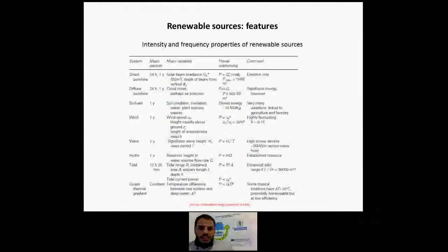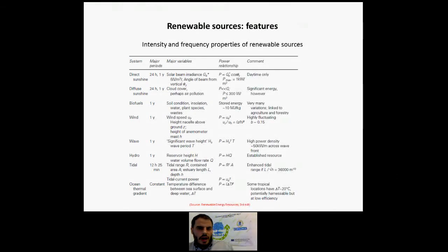With electrical systems, the end use requirement is called the load or demand. The size and dynamic characteristics of the generation need to be matched to the load requirements. As explained before, it will be explained afterwards in energy conservation. Money spent on energy conservation and improvements in energy use efficiency usually give better long-term benefits than money spent on increasing generation and supply capacity.